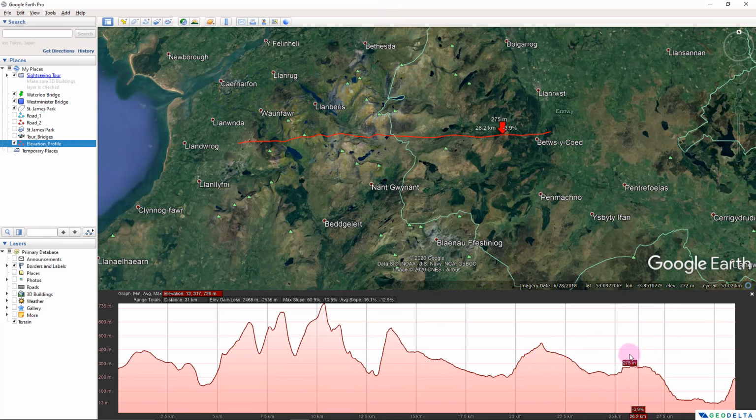the add path tool. So what you see over here in this graph, if you look at the y-axis, it's the elevation, and if you look at the x-axis, you can see that that's the distance. If you consider this starting point to be 0, you can see that this is the horizontal distance across that line stretch, and you can see how the elevation varies. So the highest appears to be somewhere over here, which is about 728, and you can see how the elevation varies across that line stretch.